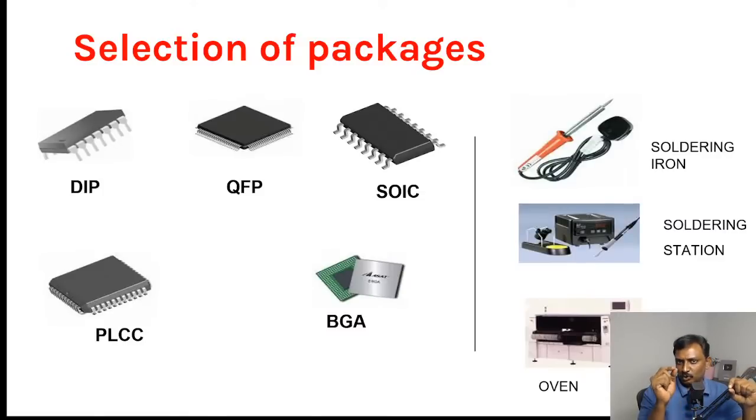If you choose a SOC, then you will be getting only the BGA package. You should have knowledge of doing schematics on BGAs, it has a complex layout process, and you also need an oven to mount the IC. You could do it, but you could also get the job done by an assembly house, paying around 1000 rupees for one IC just for soldering.